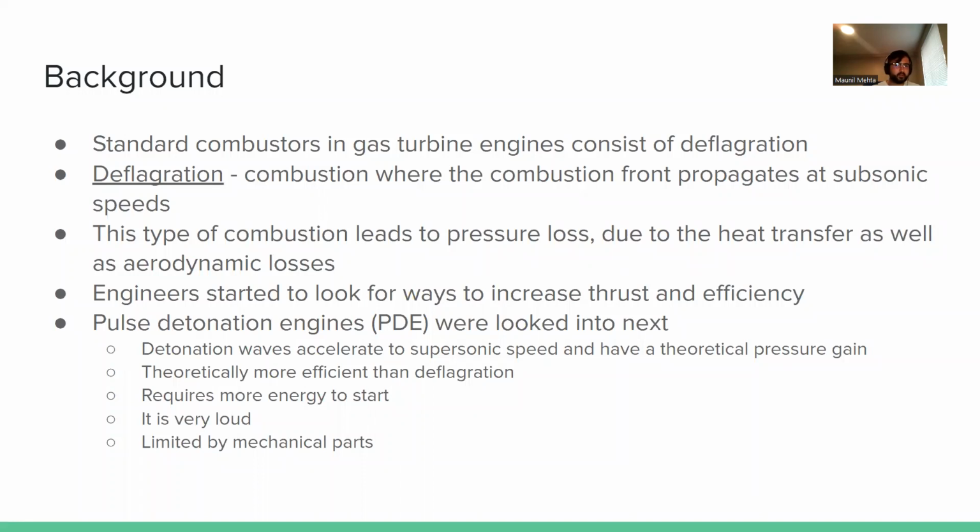Standard combustion in modern-day gas turbine engines consists of deflagration. Deflagration, the term which is underlined, is a combustion process where the combustion front propagates at subsonic speeds. Because of the modern design of combustors, the deflagration combustor is open to pressure loss from heat transfer and aerodynamic design. To combat this, engineers started looking for other possible methods of combustion.